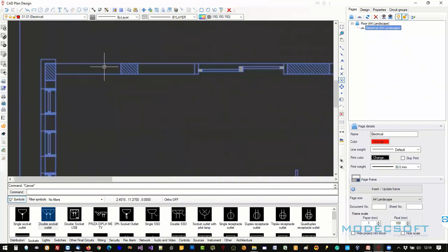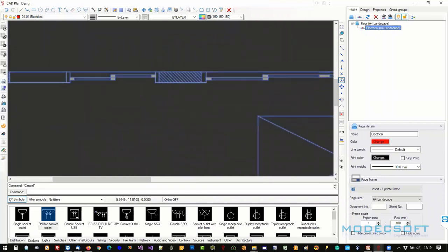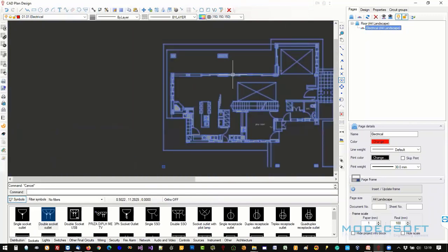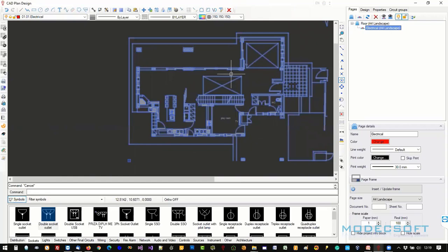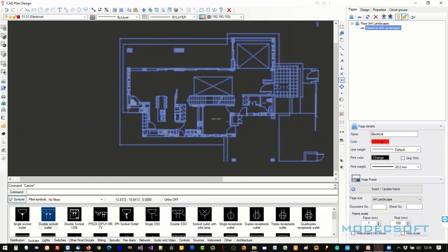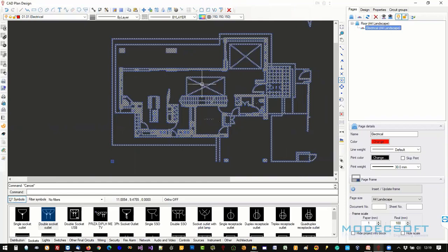So for example, you're going to have lines, rectangles, and other figures that are all part of this reference drawing. This can be done through this action here, Bind External Reference. We need to do that when we want to share our drawing with other users, because the other users will not have that specific external reference drawing. Or if we want to leave it as it is, we need to share the external reference as well.